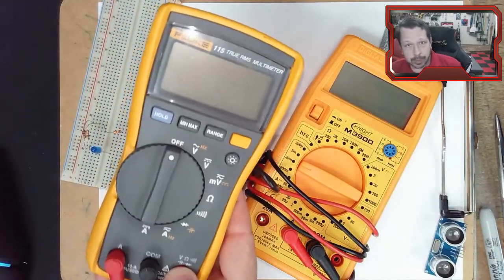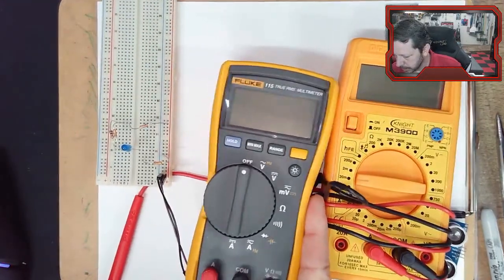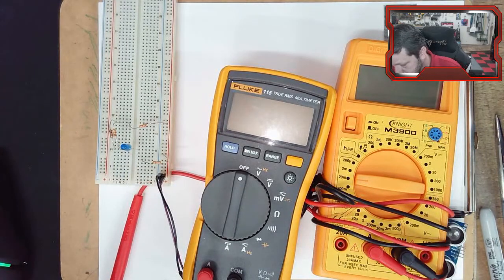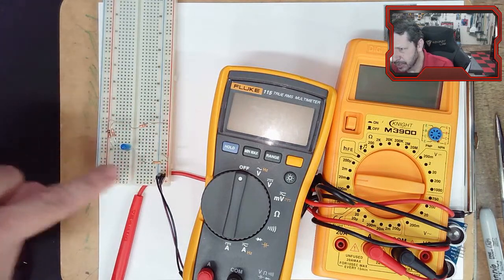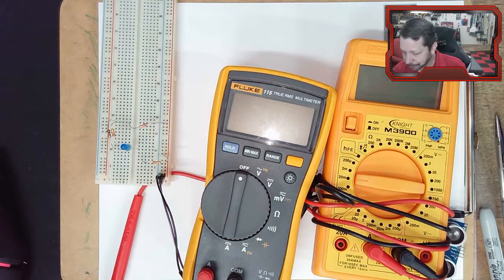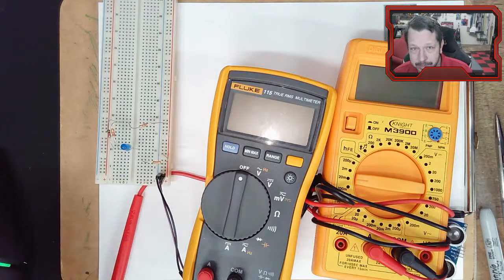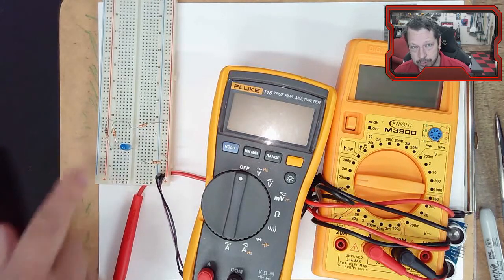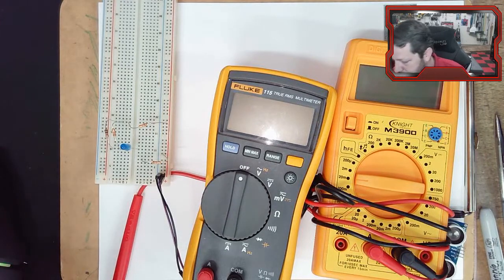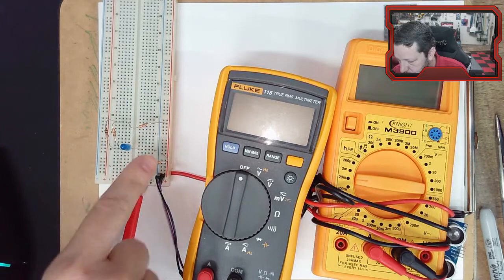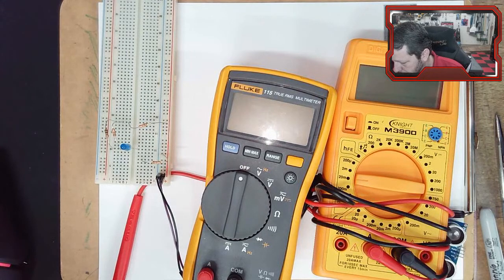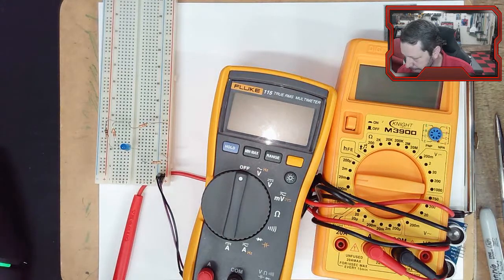Now there were a couple of things that we were having trouble with. One was measuring current. Everything else was fine, measuring resistance and all of that. There were some things we had to remember: when you're measuring resistance in a circuit that's built or constructed, it's probably going to give you the equivalent resistance from point to point, not the resistance of an individual element at those 2 points, because there might be multiple elements connected to that point. That was one thing. Also, if the power was on in the circuit, we weren't going to be able to get a good resistance measurement either. Then we tried to measure current, and I did, well, one thing wrong for sure.